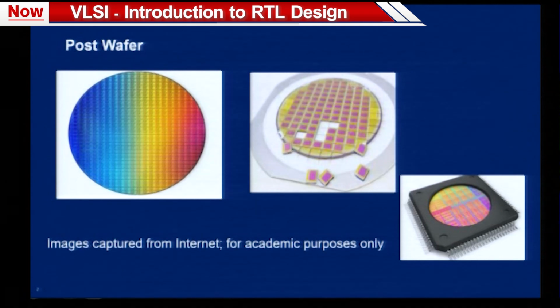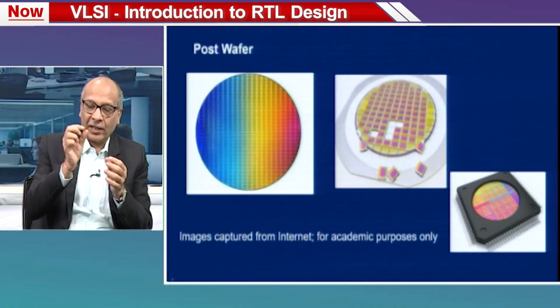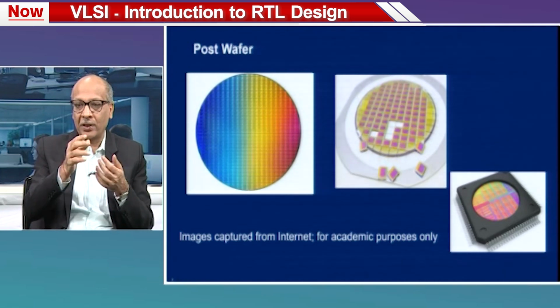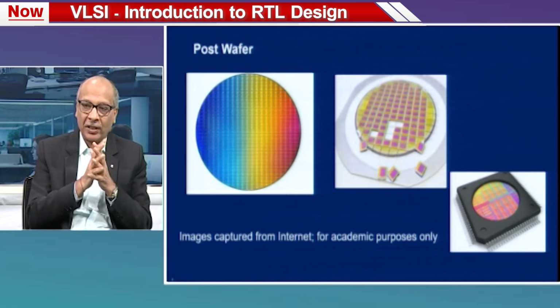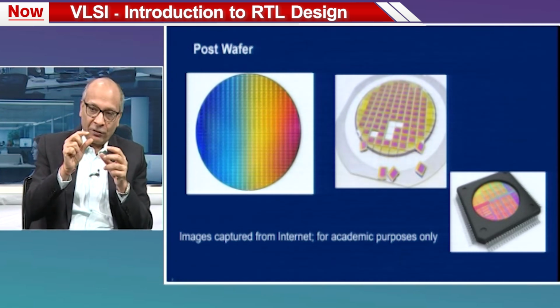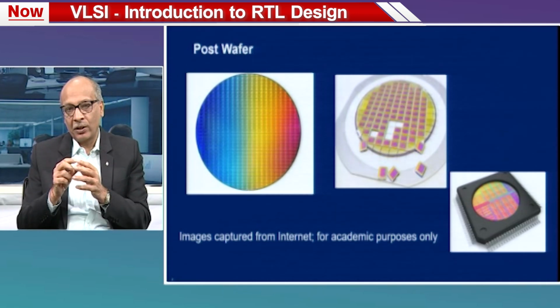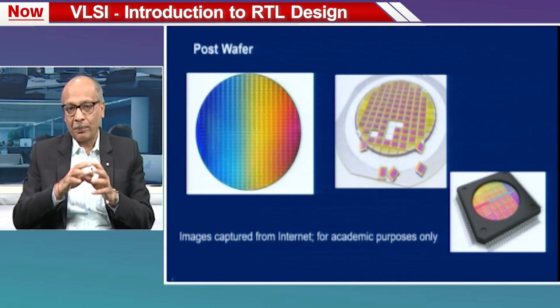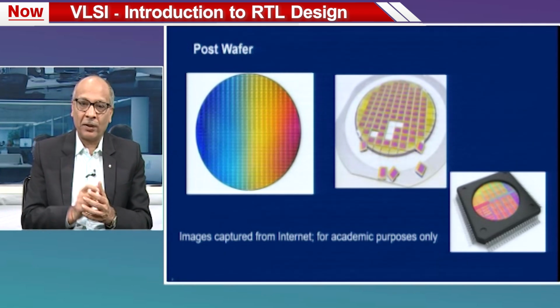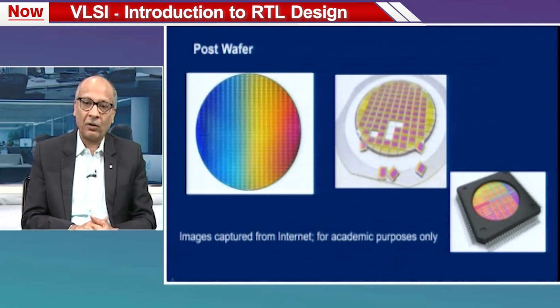Once the wafer is fabricated, each die is individually taken out. The wafer is broken into multiple pieces. You are seeing these orange pieces, these are each dies, and each of these dies is tested individually, and after testing for any manufacturing defect, it is packaged, and that is what you see in the market, what you know as a semiconductor or IC or chips.